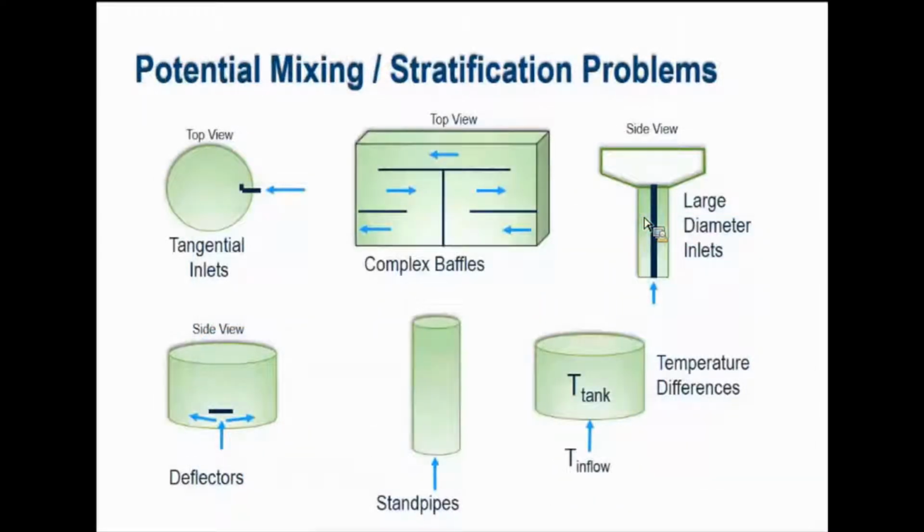So keep in mind, lots of different ways that water can enter tanks and leave tanks. Maybe it's a clear well, like the box version here. It's moving as flow through the system. Maybe you've got really large diameter tanks where right at the middle, it mixes really well because water's coming in and out. But at the far reaches, the outer perimeter of that large diameter tank doesn't mix so well. So we can handle kind of multi-mixing combinations in tanks.